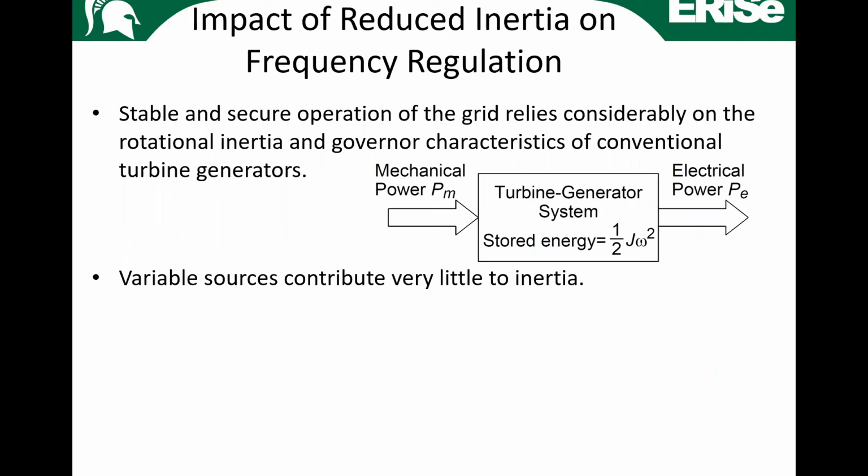Okay, but if we didn't have enough generators like this, then the slowdown would be perceptible, so you would feel that dip in frequency. Conversely, if the load drops, then this generator speeds up a tad bit. Again, if the inertia across the grid is high enough, you won't notice that pickup in the speed. It's going to be very, very tiny. So this is how we maintain frequency in the grid.